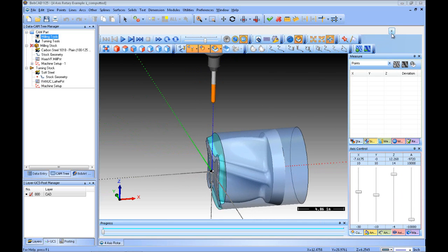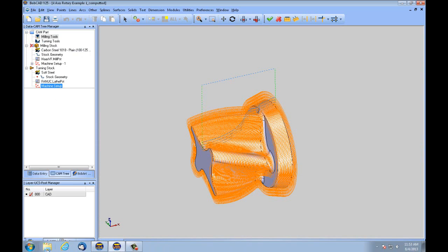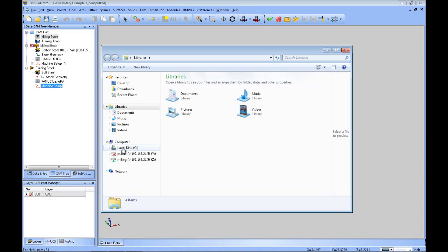Now let's go back out of here. Let's go back in and add some geometry to the machine. The first thing I need to do is go into my C drive. What you'll want to do is have STL files of all the different components saved out. And where you want to orientate them in the CAD window, the grid 0 would be that same rotary 0 that we were looking at for the simulation and located all of our numbers from.